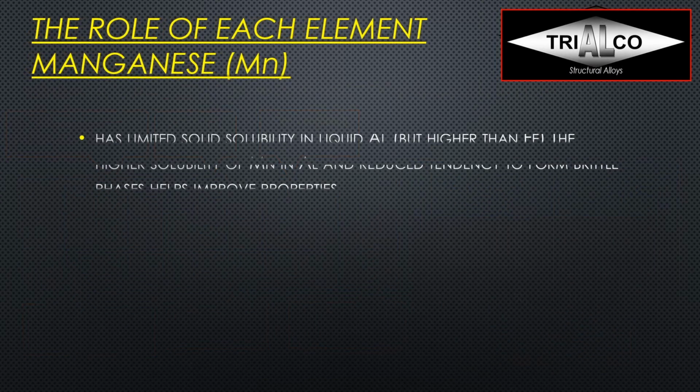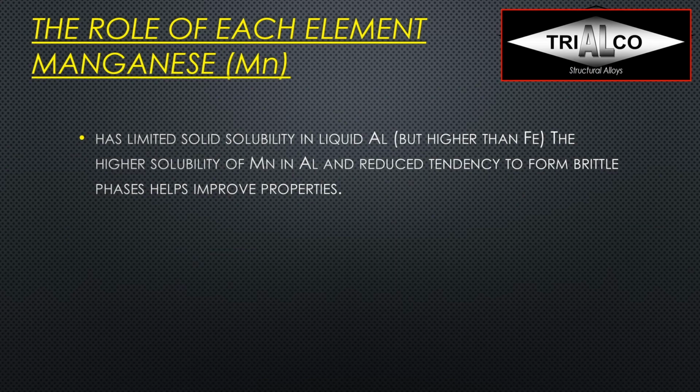So now let's have a quick look at manganese. Manganese is used, of course, in the wrought alloys, in the 3000 series alloys, but in casting alloys it's mainly used in die casting alloys or in secondary aluminum silicon alloys, and there it is usually added as half of the iron content. In die casting it is used to reduce die soldering and replace iron for higher ductility.